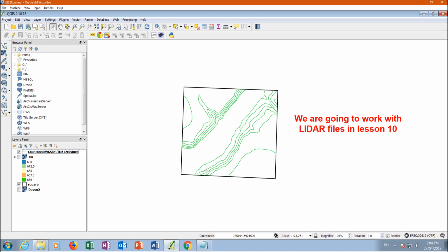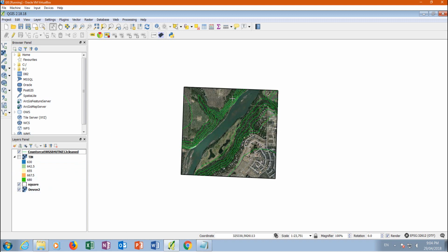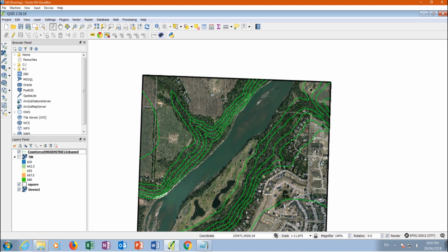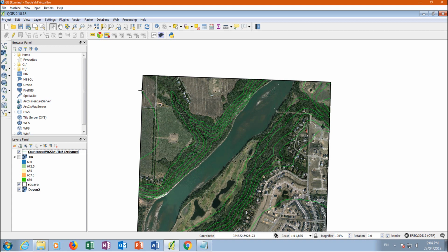And the resolution for that kind of file is really good, and the model you are going to get is going to be very close to reality. Okay, in this case we are working with a 50K. That's a very coarse resolution for a small area like this one, but that's the information we get for free. If you want better resolution for the digital elevation model, you have to pay for more accurate information.